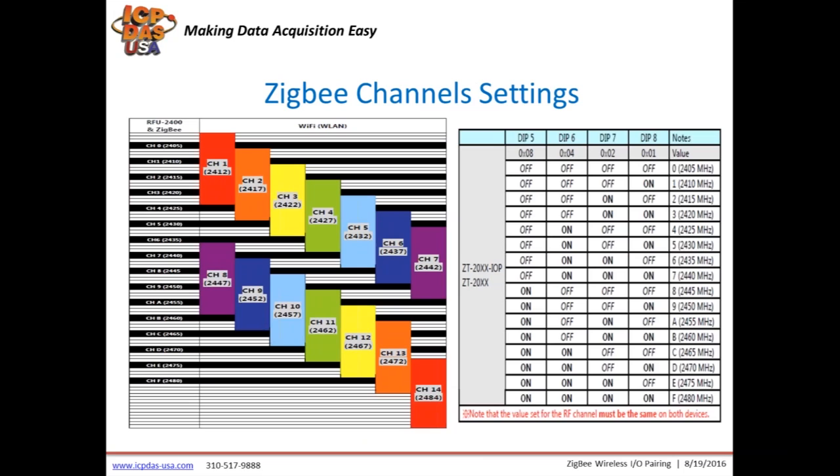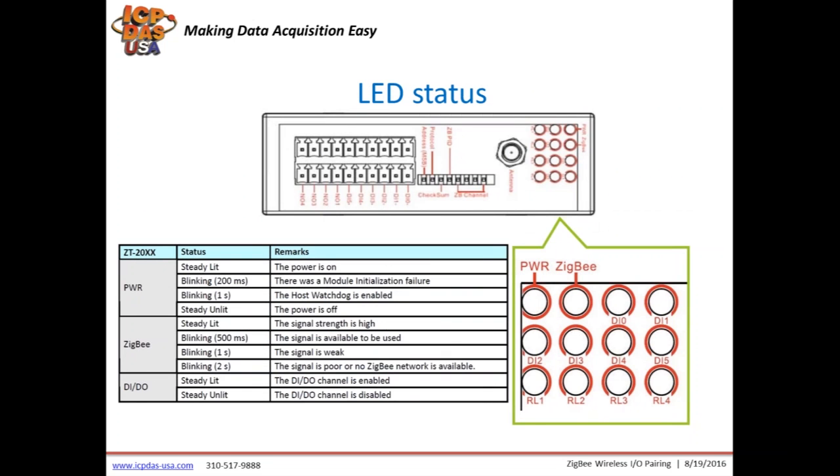Because of this, you want to avoid interference between these devices. Many cell phones have network analyzers which will tell you what Wi-Fi channels are being used by other devices so you can avoid using these channels. We also provide a list in our manual which shows some suggestions. If you have multiple Zigbee networks, you can select different channels and have multiple networks running at the same time.